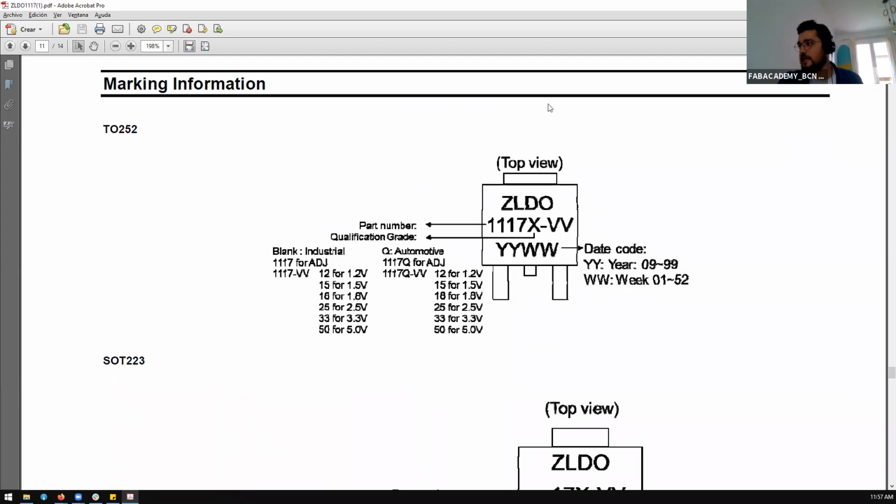They state a size, like let's say a pad of 10 millimeters by 10 millimeters, when you have to solder this part to part of your PCB. So that part needs to be soldered to a big part of the PCB, not a trace. Let's say an empty part of the PCB, to allow heat dissipation. So actually you use your PCB board to dissipate and work as a small heat sink.